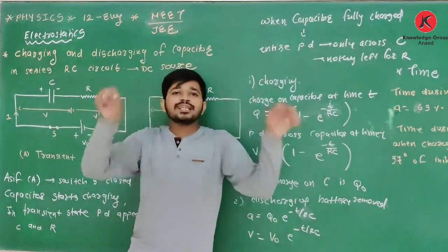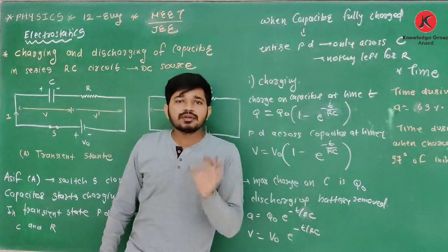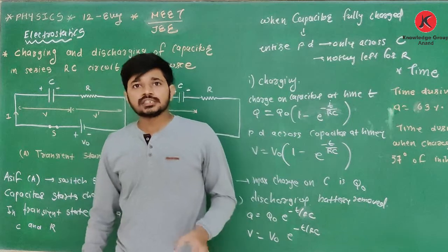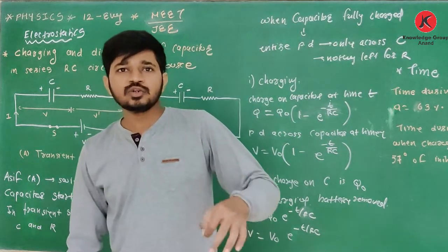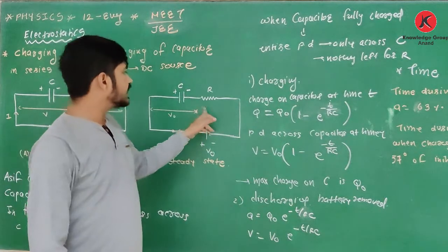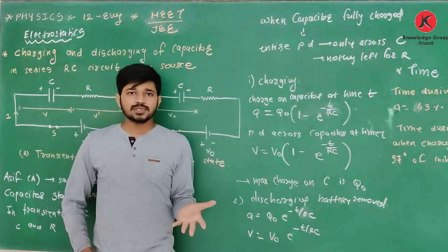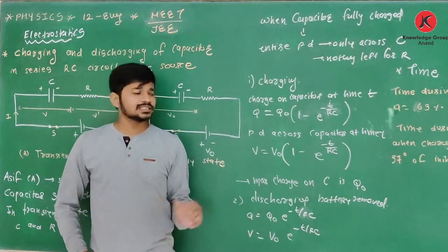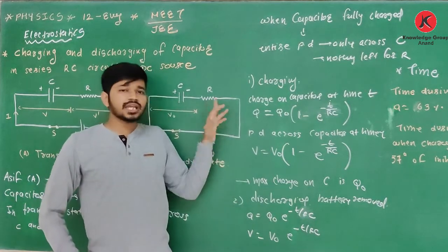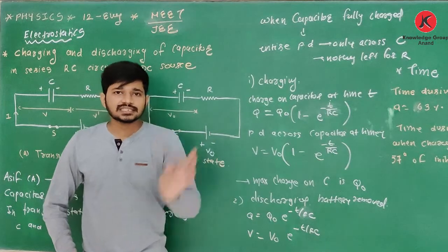condition. So whenever in a circuit you are given capacitors as well as resistors, and the capacitors are fully charged, you can neglect resistors in series. Simple. Yes or no? Yes it is. So here you can neglect these resistors. In steady state, you can neglect this resistance.